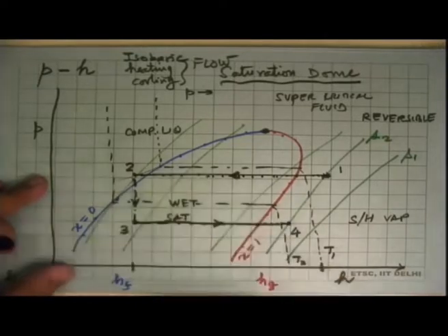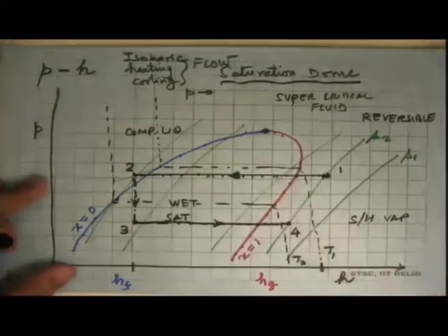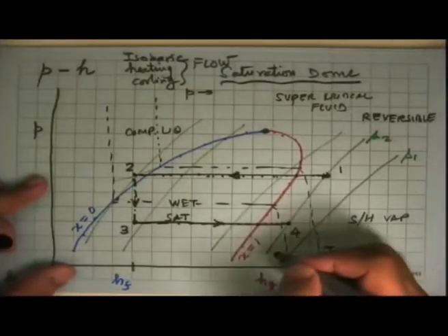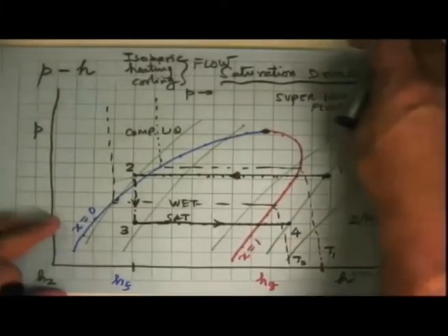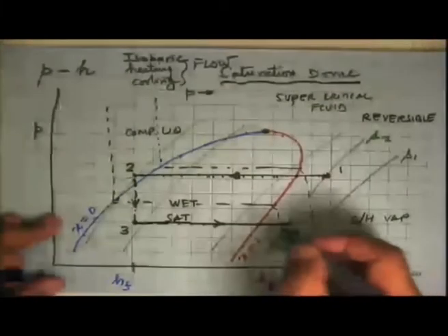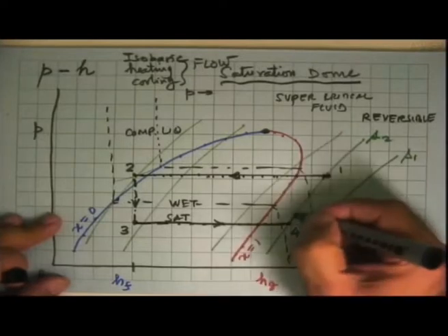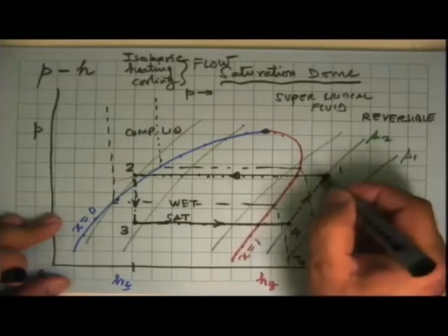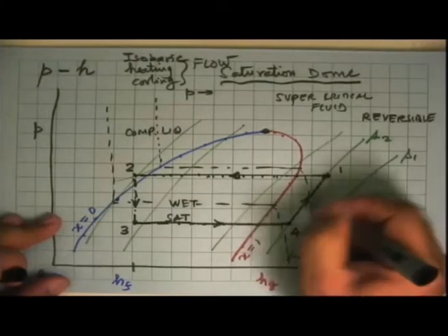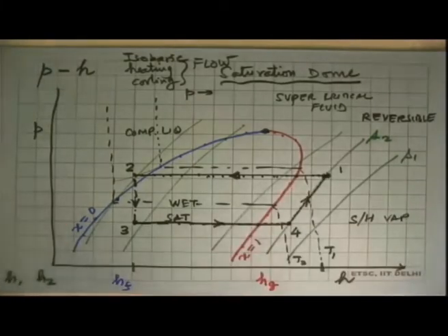And to complete this refrigeration cycle, we say at this point it enters the compressor, and if we assume that the compression process is reversible adiabatic, it means that it is an isentropic process, then the process inside the compressor will go along a constant entropy line. This will again have to be a solid line, and that is our compression process.